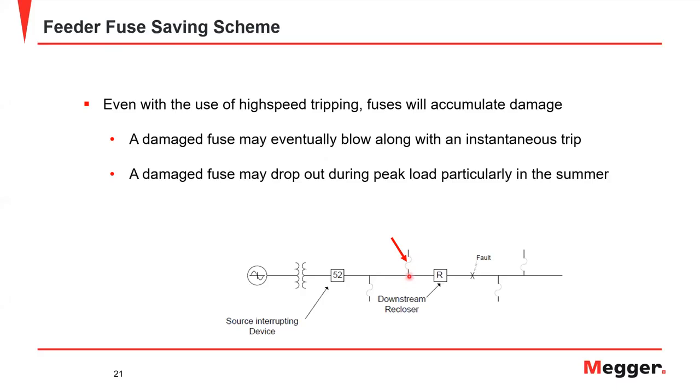Most fuses actually have a spring inside that holds tension on the link. The spring is used to accelerate the movement when the link parts, so that it helps to interrupt the fault. That tension, a little bit of accumulated melt, if it gets hit with 3–4 faults over time, a little bit of micro vibrations with the wind going on, and you can have a fuse just give up and drop out at an unpredicted time. It might be associated with another fault on its branch, but it might not be. It's very hard to say. It could be the summer sun is the final factor.